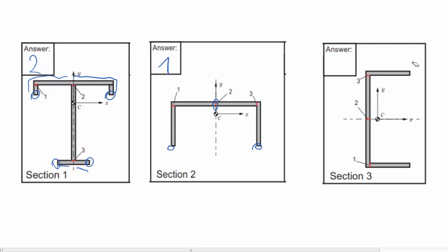Section 3 is a regular C-section. In this case, we again know that on the open edges the shear flow will be 0, and from there on it will only increase towards the center. In this case, we know that on the vertical member the shear flow will have a parabola shape. Therefore, point 2 is the point that will have the highest shear stress.